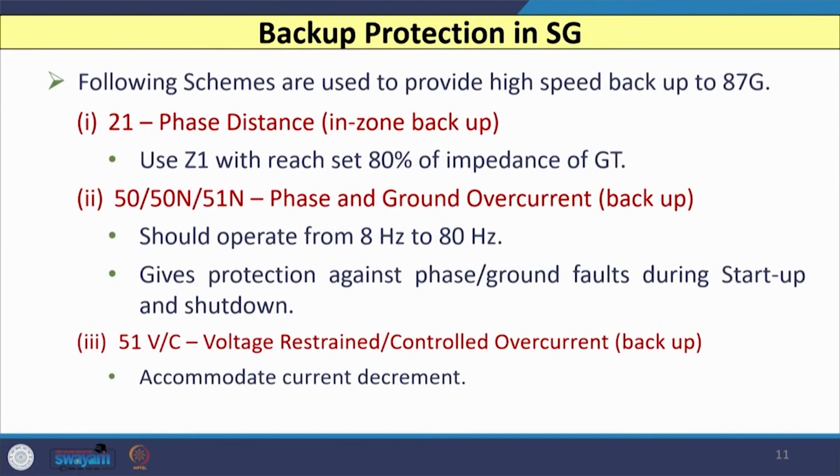fault. Till now we started our discussion with the features of the digital relays, and we have seen that based on 3 standards we can refer to those standards. Then we have discussed the important characteristic of 87G used for the protection of generator, and at last we have discussed turn to turn fault protection, for which we need two parallel windings, and again we have to put the CT and go for transverse differential protection.